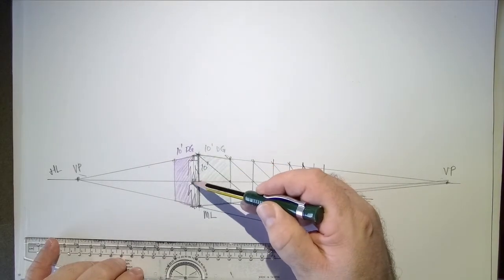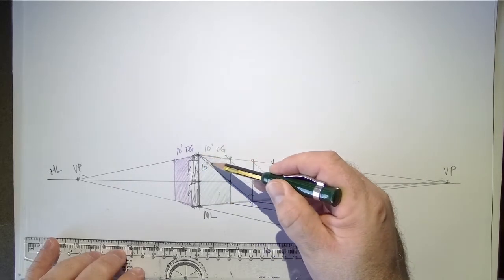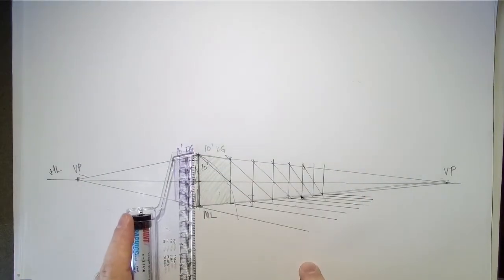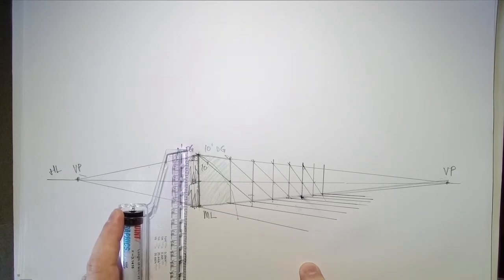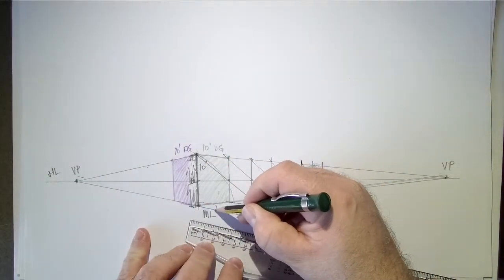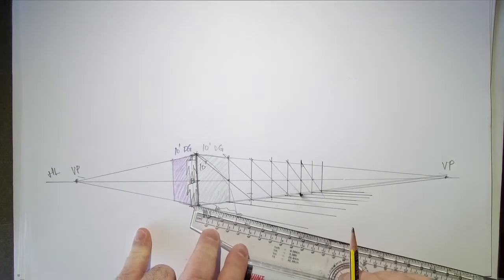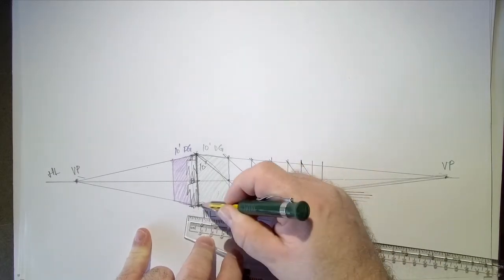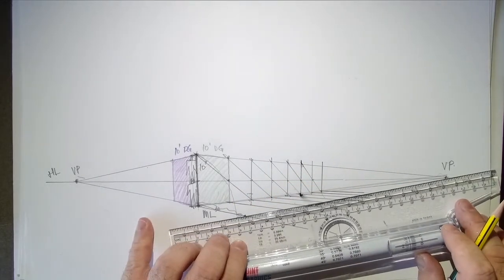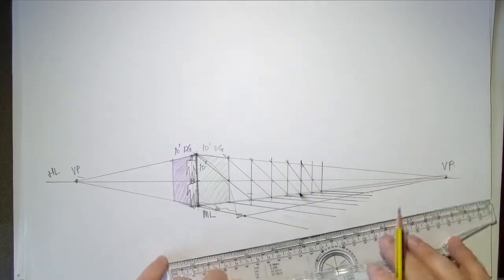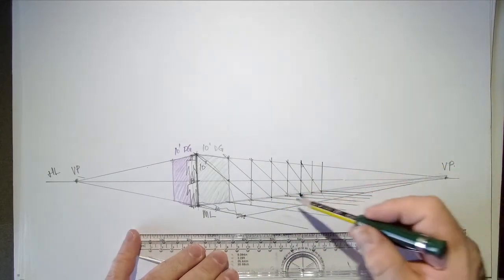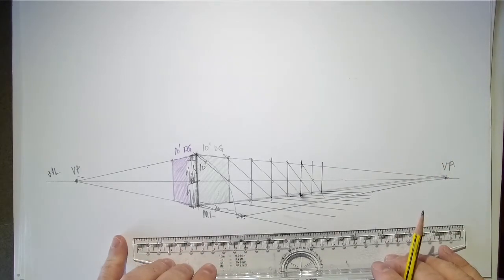Our two friends are getting tired, and so they end up falling directly, clunk, like so. So this representation of measurement can be transferred down. I can see that that's approximately just under 2 inches. So if we were to imagine them falling and laying on the ground perfectly, this is approximately just under 2 inches. So that represents 10 feet on the floor plane. That will now vanish to the right. So that's the beginning of perhaps a footpath width, or alley width, or street width, something of that nature.